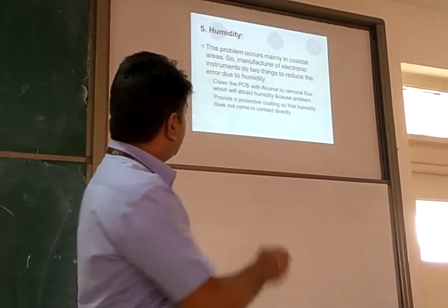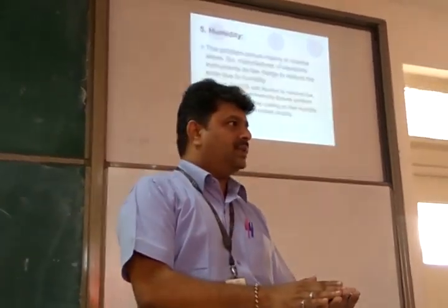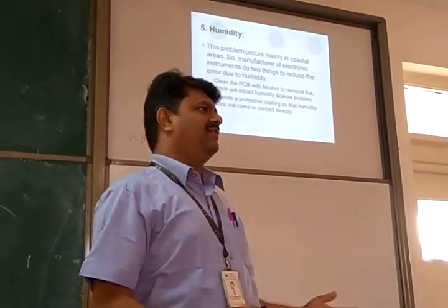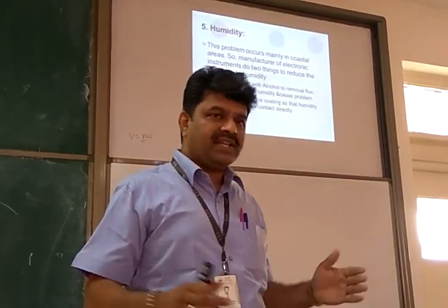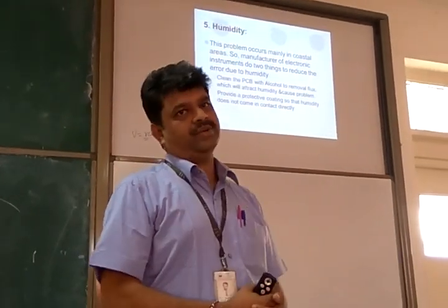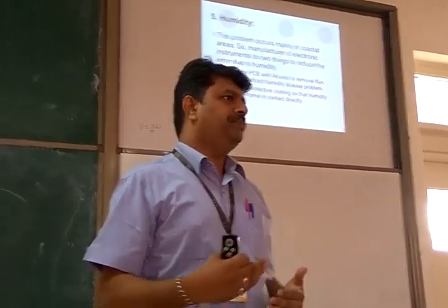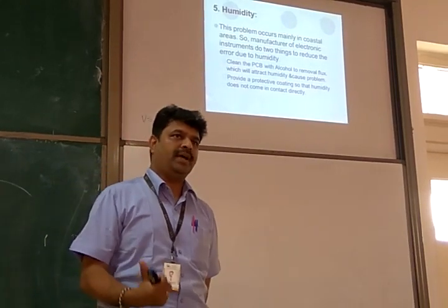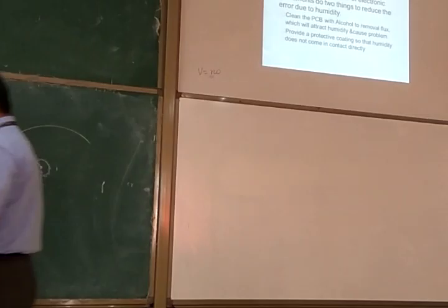The problem is because of humidity. The humidity in the air gets absorbed by these electronic circuits and that created a problem. This was in the initial days of development. Nowadays, no instrument gives trouble because of humidity. But if something is not taken care of like that, it will result in problems in the instrument. It will give erroneous readings and you will not know the cause. So you should be careful about the material that you use, whether it is hygroscopic, because humidity can cause a problem. Okay, we stop here.